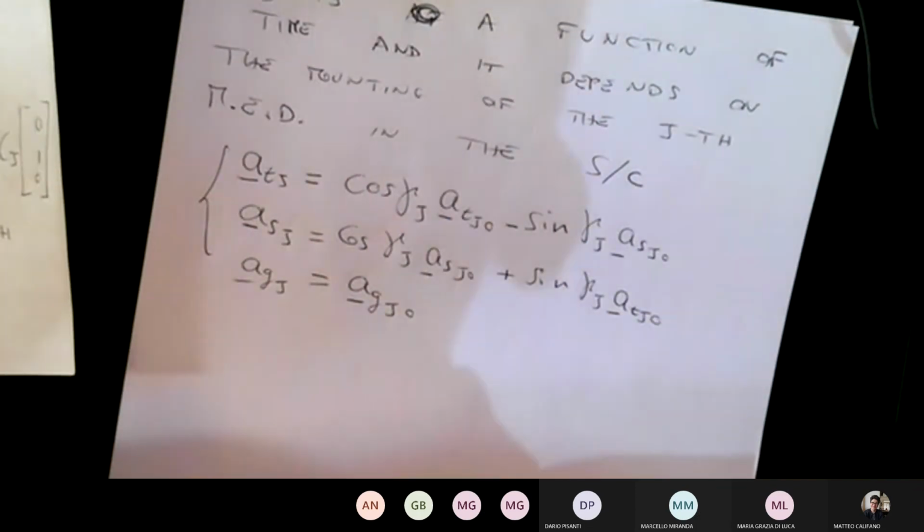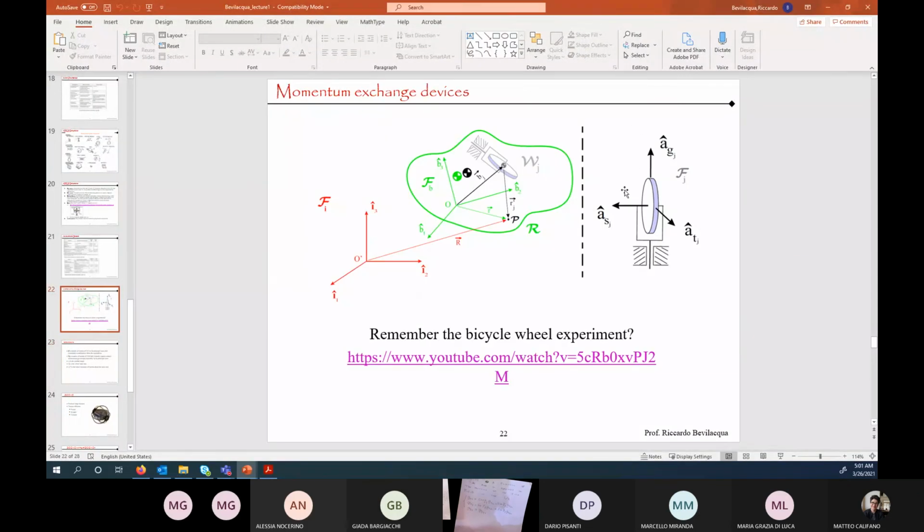If you go back to my slides and look at this image here to the right, you rotate through an angle gamma about G. Imagine that you freeze some initial position for S and T, then the instantaneous positions of ASJ and ATJ will be moving in the same plane as AS and AT at time 0, and their orientation will be represented just by the angle gamma. And as you're rotating about G, the direction of G doesn't change. It's the fixed axis of rotation. Okay.